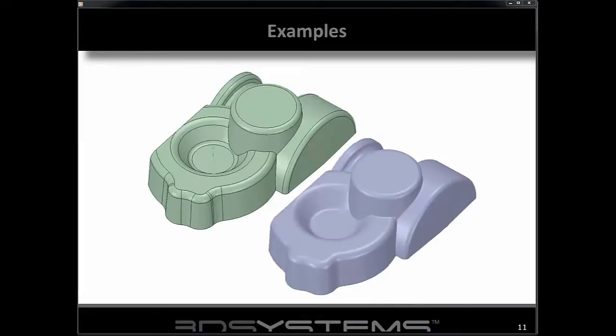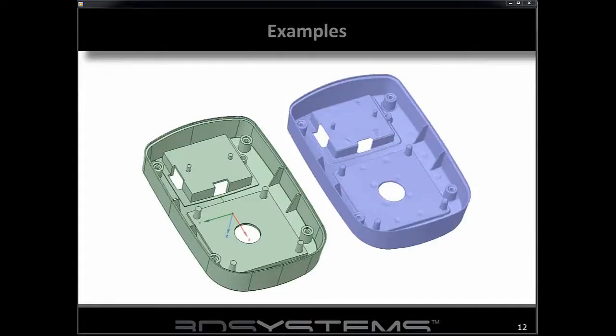And lastly, a few other simplistic examples of the types of extruded, revolved, flat, cone, cylinder shapes and things like that you can create. A little bit more complex case here is a part that has some offset to it. You can see that purple scan data on the right has all the imperfections you would expect, with the tooling marks and some areas, the little plastic nubs that were scanned. Of course, you don't need those. Those aren't incorporated into the actual design, so you ignore them, but all the other pieces you want can be fairly easily extracted from the scan data.